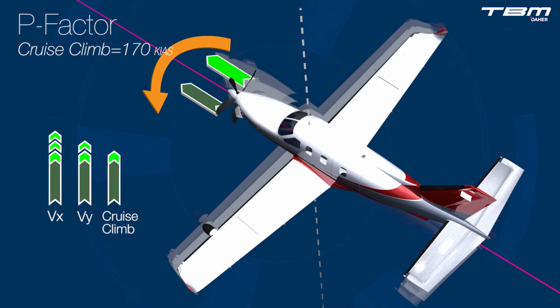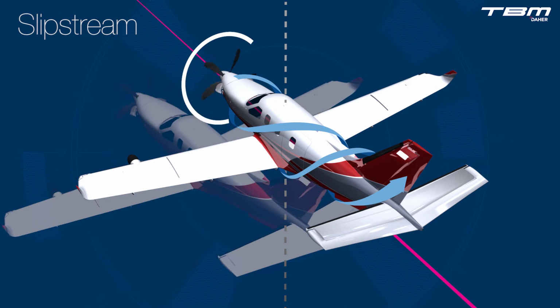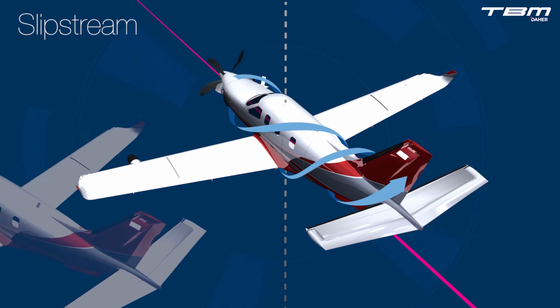As the angle of attack is reduced, less and less rudder force is required to counteract the left turning tendency. The propeller slipstream exists throughout the speed envelope and creates a nose left turning tendency, which is pronounced at low airspeeds and decreases proportionally with increases in speed.